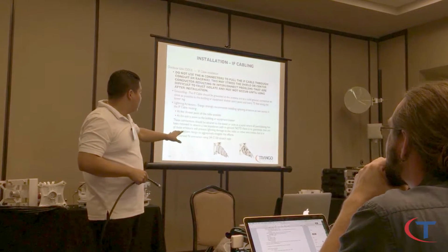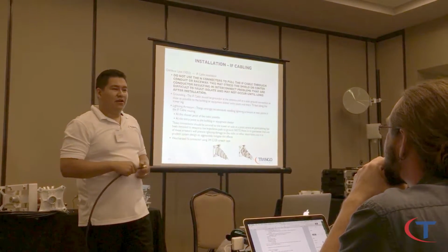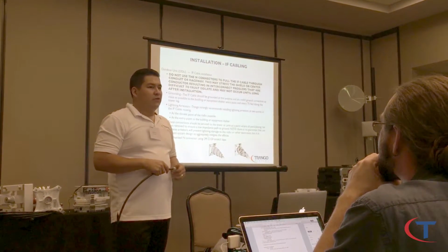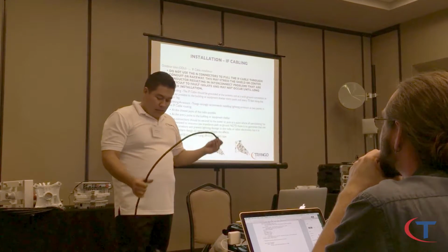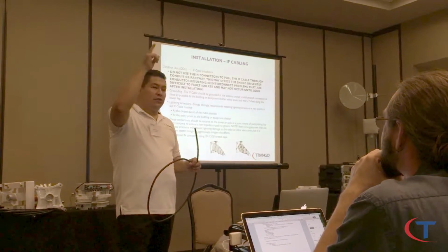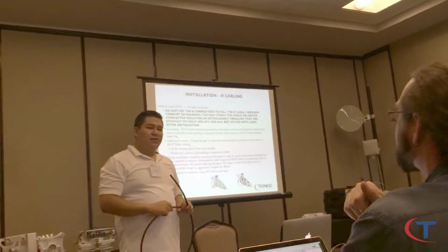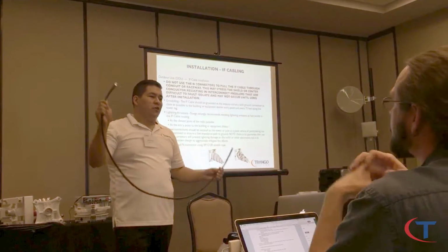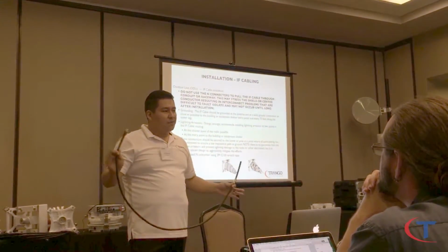So now you weatherize this. Over time, it's going to get clunky, it's going to get sticky, so if you're going to replace it, you typically have to replace the entire end connector. But I would recommend having a polyphaser. Have your cable run done and have a polyphaser at the bottom and top, and then just have a jumper from the polyphaser to the ODU. That way, if something happens, you can just replace the jumper and you're done.